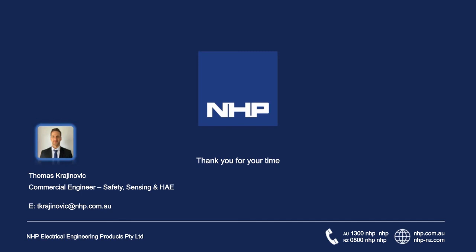Okay, so there are a few technologies that you could use in multiple circumstances as a kind of default solution. But it really does depend on the application and the cost you want to associate with a default solution. So, for instance, you could use ultrasonic sensors in a lot of cases, but they are more costly, and depending on the output you want, whether it's discrete levels or measurement, there's a little bit more time involved and integration in tying off that solution.